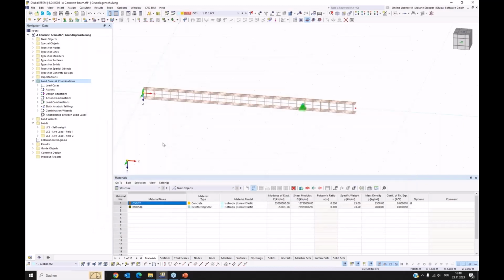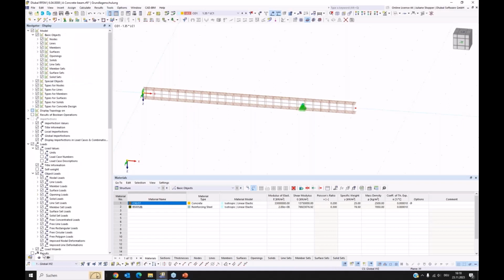Okay, then we have to fill the loads. We have them prepared, the cases, but we have to define the loads also. Therefore, we have here a folder loads, and these load folders, the specific, were created after I did define these cases. And I have now a folder for self-weight, and I have to fill this. The self-weight is already existent as I activated it, and it's calculated automatically with the material's specific weight and the cross-section. And you can have a look at it.